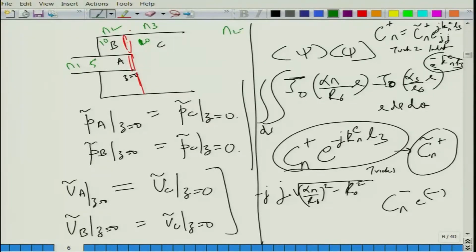Generally we consider n2 as equal to n3, that is, the number of first few modes in the annular cavity and the expansion chamber are considered the same. Inlet pipe, because those pipe diameters are typically quite small compared to the chambers, about 40-50 mm for automotive mufflers. So, we consider a limited number of modes given the operating frequency and so on.